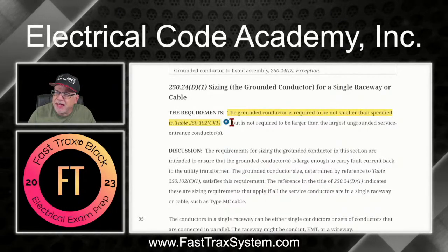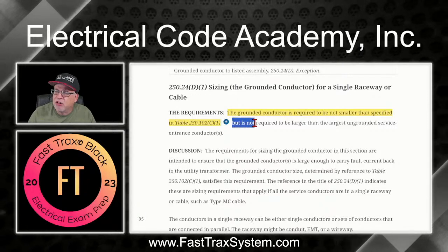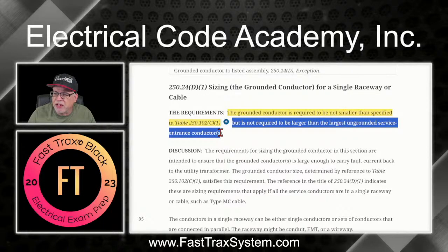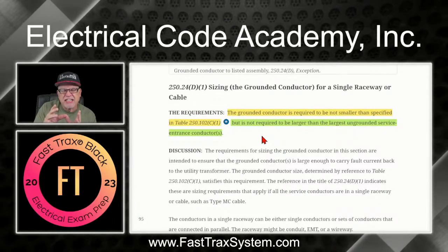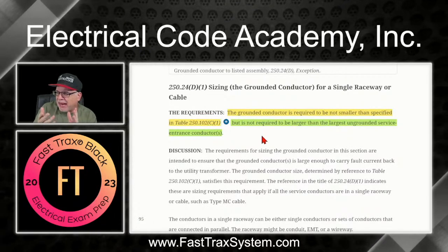Next thing to remember, in sizing that grounded conductor, it's not required to be larger than the largest ungrounded conductor or conductors in that raceway. That's the next important part. So if I had one raceway and I had 600 kcmil ungrounded hot conductors, and I were to go back to